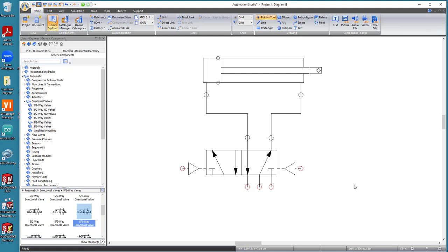And the next thing we're going to do is, in order to drive this valve, notice there are 3 ports over here. So with the default position, we want compressed air to go in this port, and it's going to go in the direction of the arrow. It's going to push into this and push that cylinder to its retracted position, and air has to flow out of this port when that's happening. So we're going to need a pressure source and also an exhaust.